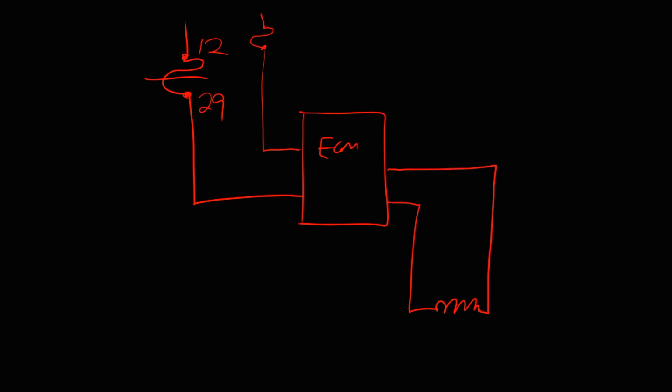When you turn the key on, the computer with this power feed was half alive. So this half of the computer is alive, and this half is dead, and it ended up pulsing that solenoid incorrectly. The counter EMF of the collapsing magnetic field of an inoperating solenoid partially caused voltage to rise and backfed the computer from these spikes.